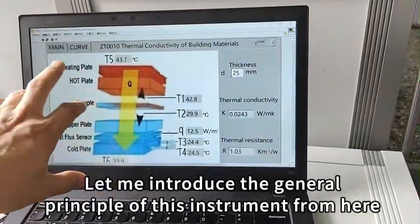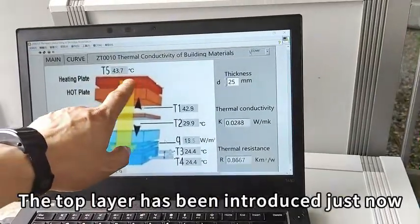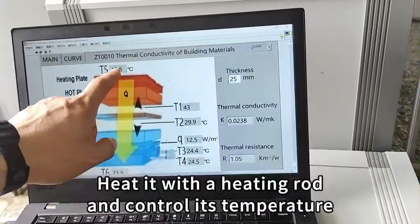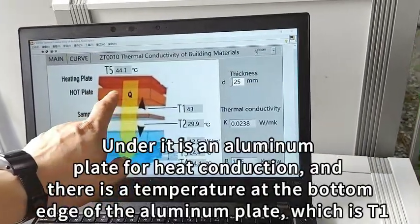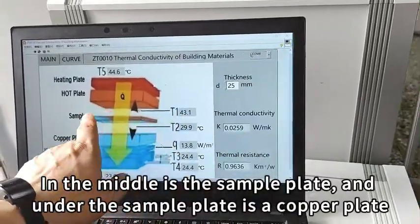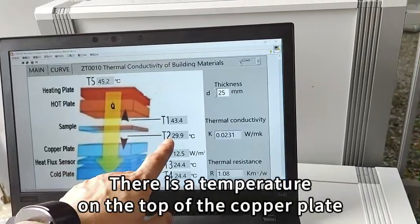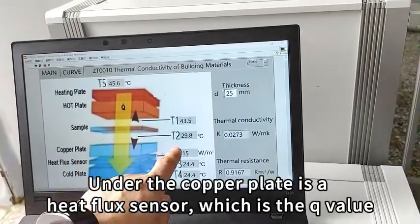Let me introduce the general principle of this instrument from here. The top layer has been introduced just now. The top layer is the heating plate, and its temperature is controlled by the temperature controller just mentioned. Heat it with a heating rod and control its temperature. Under it is an aluminum plate for heat conduction, and there is a temperature at the bottom edge of the aluminum plate, which is T1. In the middle is the sample plate, and under the sample plate is a copper plate. There is a temperature on the top of the copper plate. Under the copper plate is a heat flux sensor, which is the Q value.